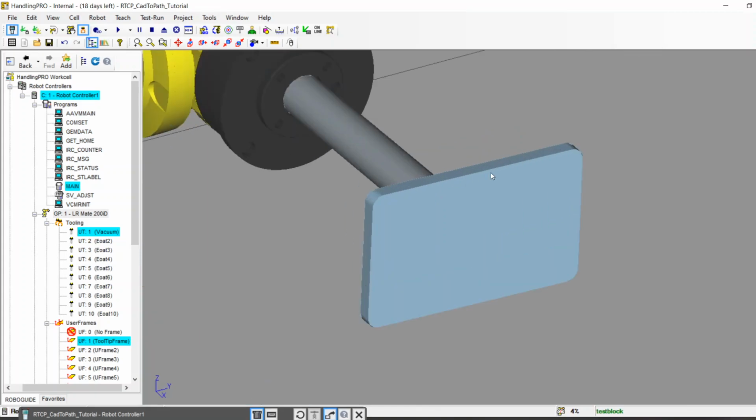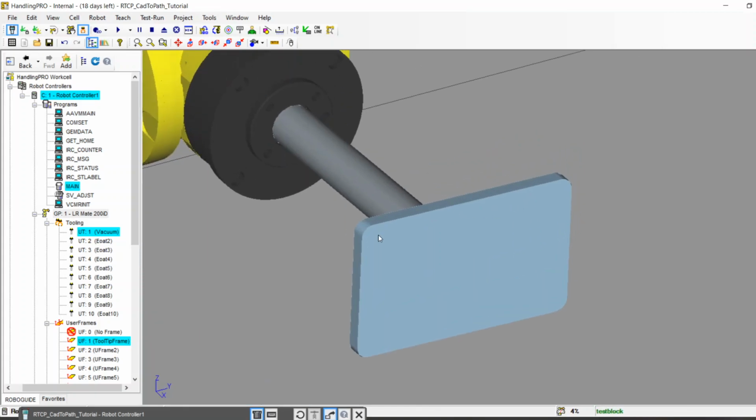Now I know that the robot will wind. I'm going to call counterclockwise negative. So being that the robot's starting at positive 90, I want my path to go around the part this way so that as the robot deburrs, it'll actually unwind. If that doesn't make a ton of sense, don't worry. It's hard to wrap your head around what's positive, what's negative. You can always change it later. That's why we test it in Roboguide. If it fails, you just flip it and change the direction.